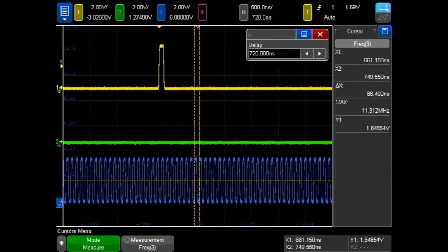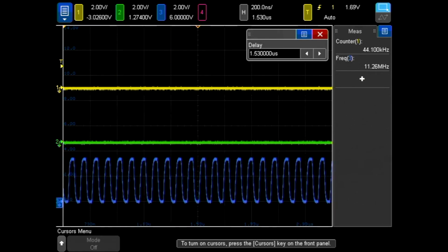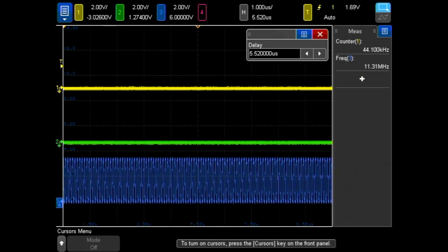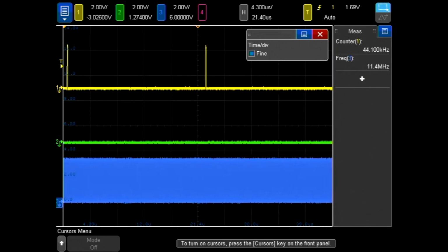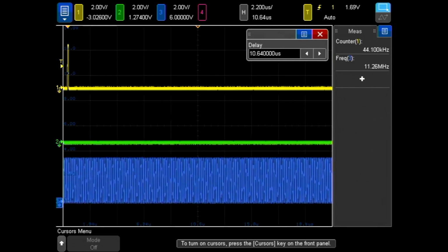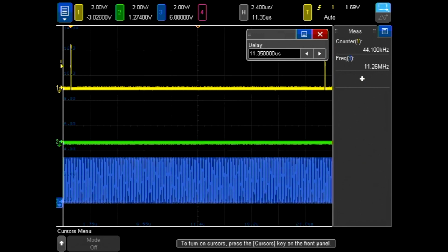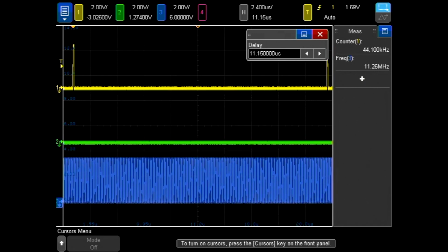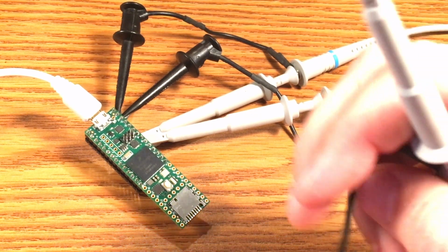Let's turn off this cursor. We don't want much clutter on the screen. Unfortunately, this oscilloscope, you can see, is not a super high resolution screen. But the idea is that we have 256 bits or clock times. Scroll back out, move this over here, and go to a finer setting. I'm going to adjust this so that we get these clock pulses right on the edges of the oscilloscope screen, so that we're looking at, there, I fine adjusted it. And this is, like with all use of oscilloscope, you spend a little time fiddling to get it set up. So here we're looking at one frame of 256 bits. Now let's come back over to the hardware, and I'll tip this up here.